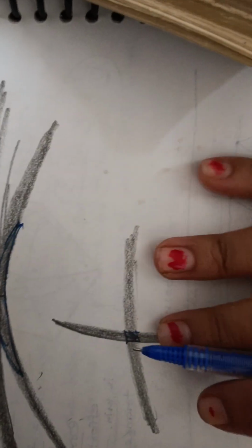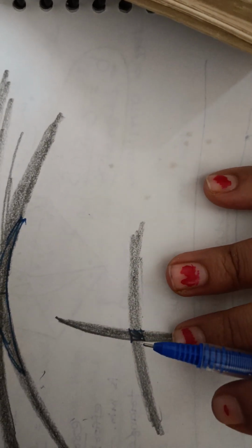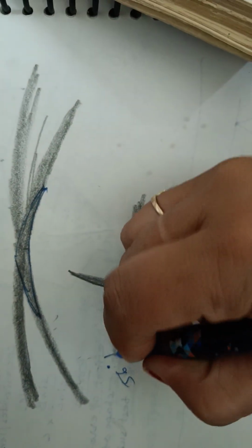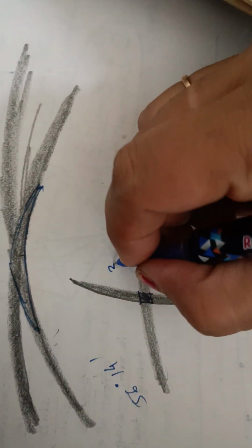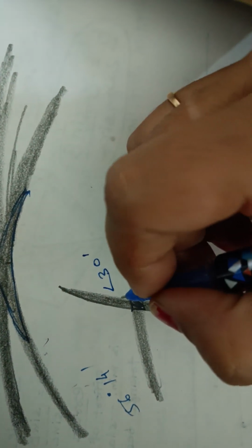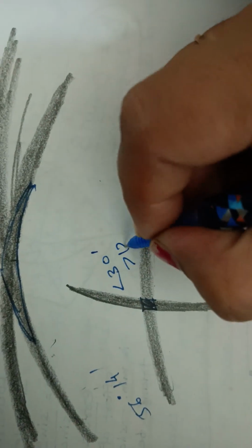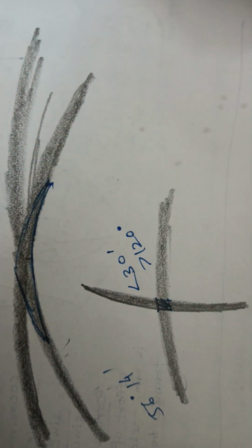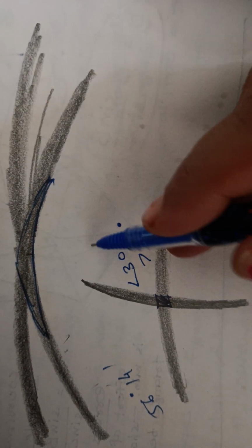So hence the base of the triangle is with the base angle equal to 56 degrees and 14 minutes. However, from practical considerations, an equilateral triangle is the most suitable. In general, triangles having an angle smaller than 30 degrees or greater than 120 degrees should be avoided, and other angles are preferred.